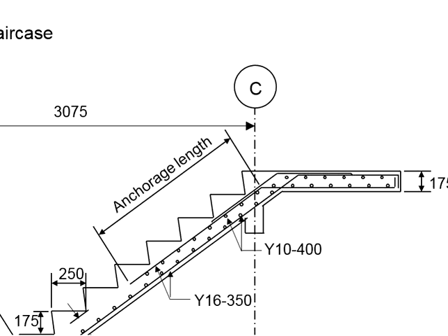If you see the longitudinal reinforcement at the bottom of the landing, you need to make sure it is also embedded in the flights with at least sufficient anchorage length. That means the reinforcement shall be bent so that it fits nicely to the inclined members of the flights.